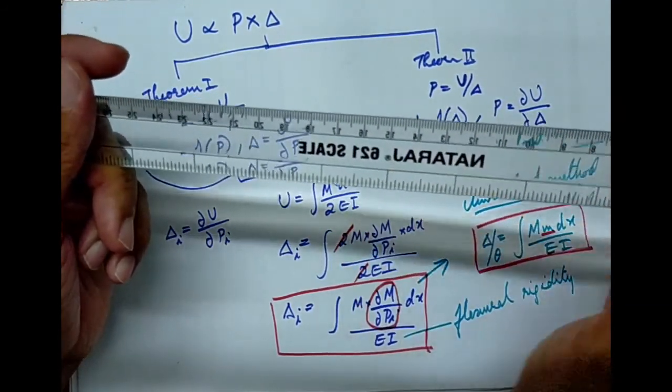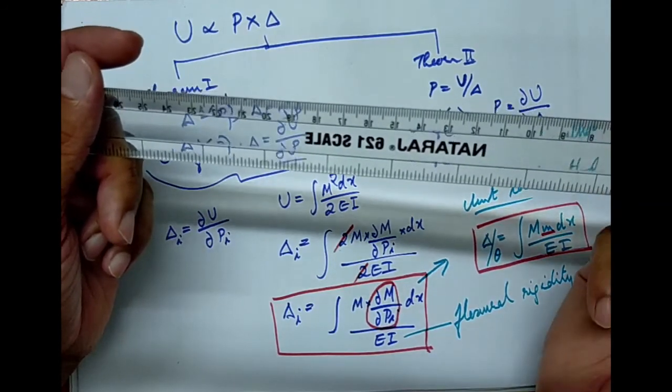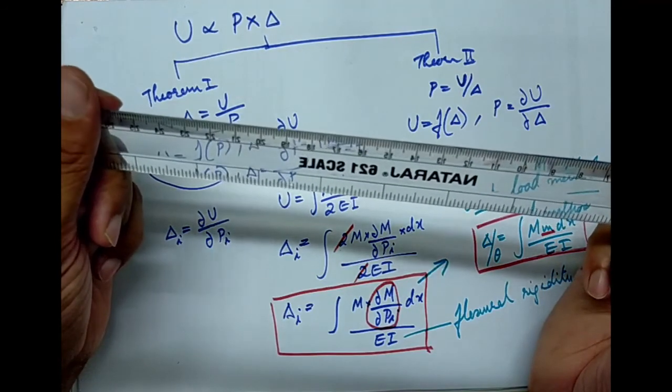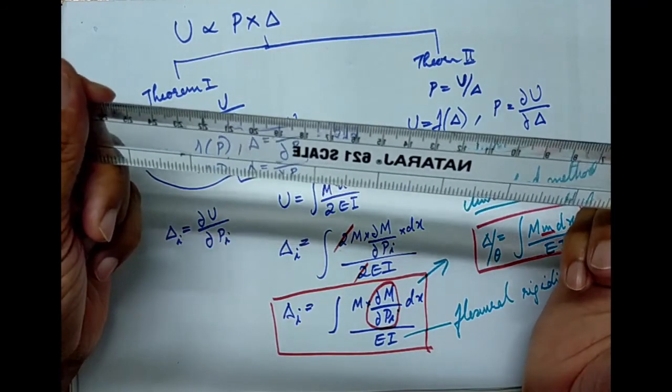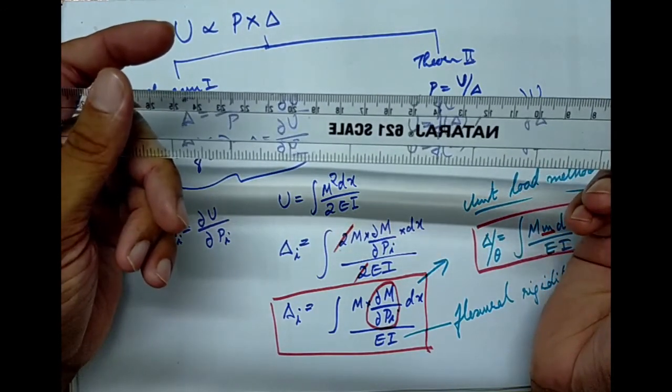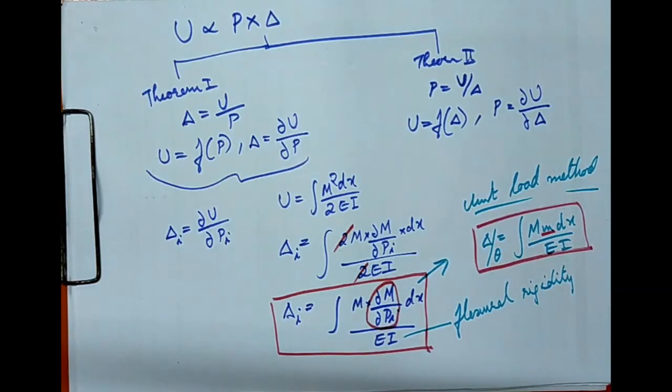Did the cross-sectional area change? Did the material change? No. The only thing that changed was the orientation of the cross-sectional area. So a parameter that takes into account the orientation of the cross-sectional area is the moment of inertia. So when we talk about the rigidity against bending moment, we will be considering not the cross-sectional area but the moment of inertia. So with the material and the moment of inertia, we get the flexural rigidity as EI and axial rigidity as AE.